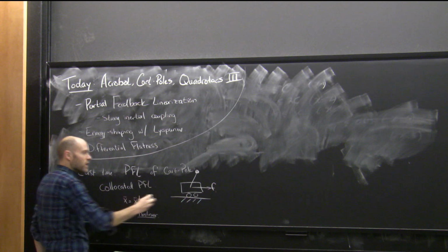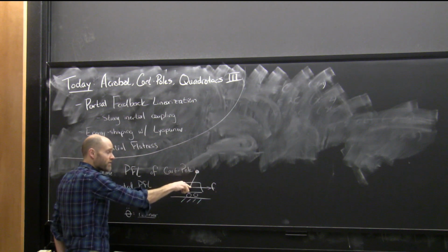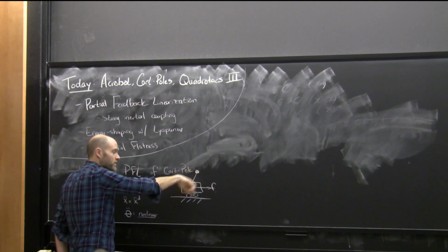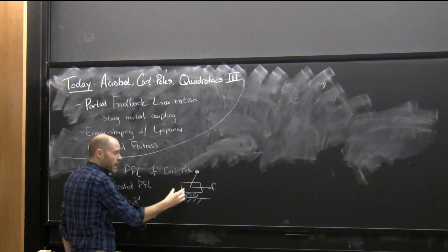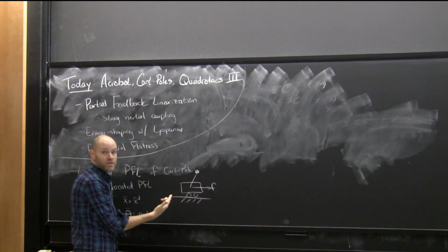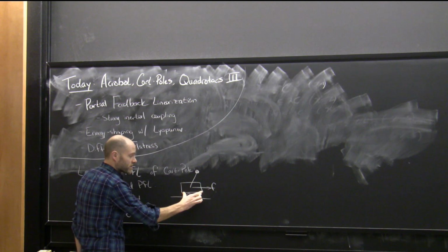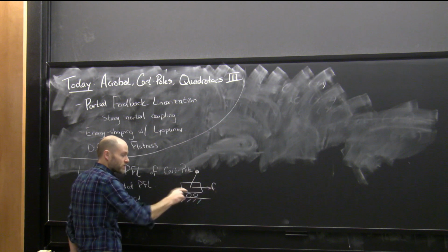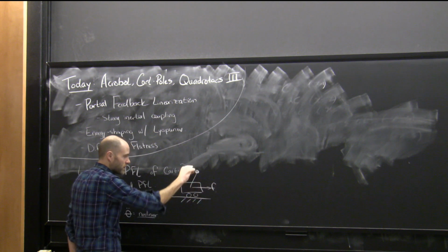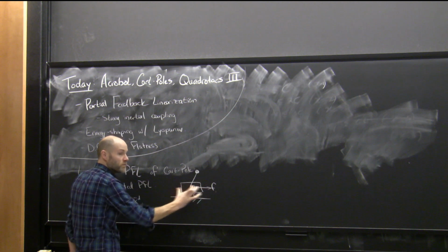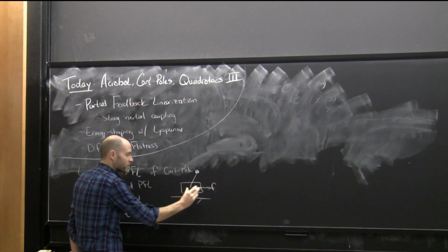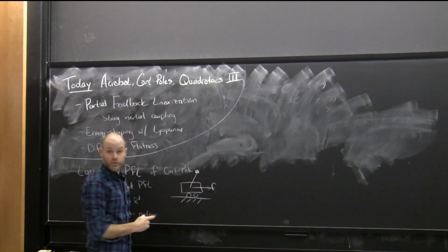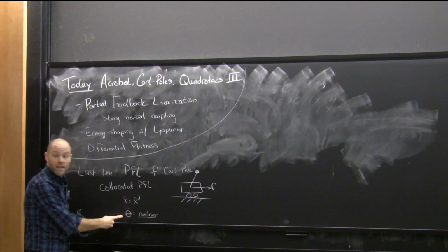The intuition there is that if we have the model, we can compute with the dynamics the effect that the pole is having on the cart. Then we can just apply exactly the equal and opposite forces to cancel that out and make the cart go back to simple dynamics. So this thing, as it swings, is going to push and pull on the cart. By default, if force was 0 and this thing started swinging, the cart would go boom, boom, boom, responding to the pendulum. You can apply exactly the opposite force, cancel out the effect of the pendulum, and you've feedback linearized one of the degrees of freedom. And the remaining one is still nonlinear.